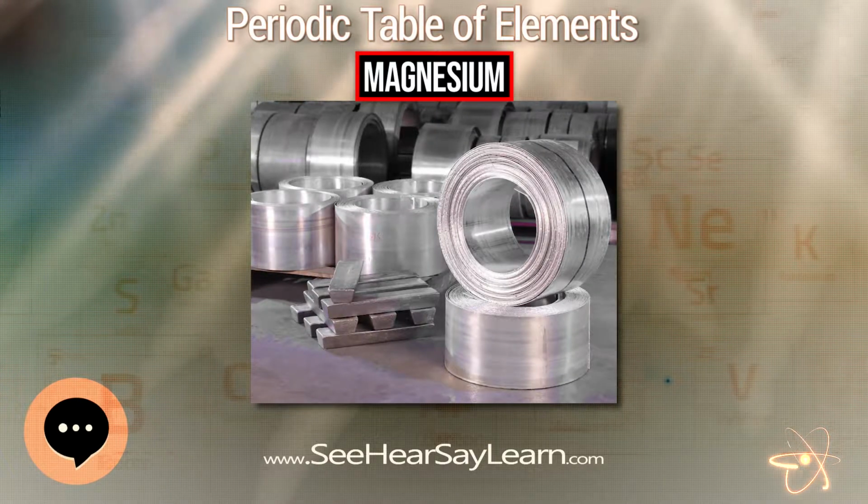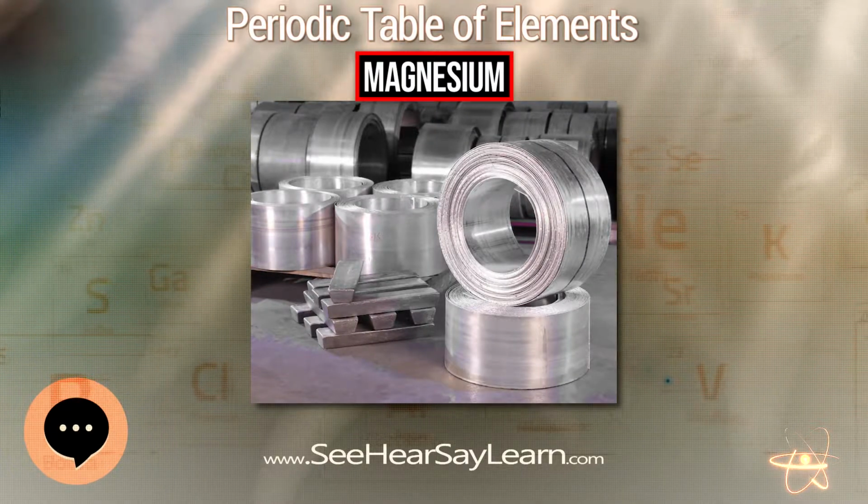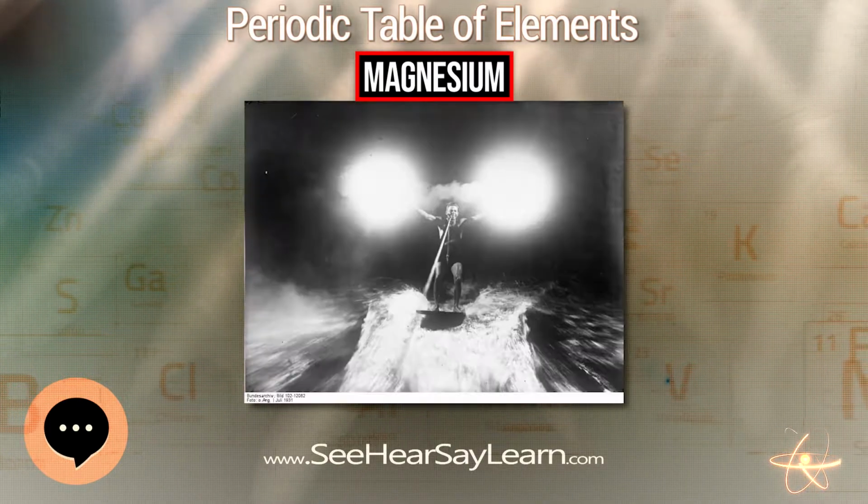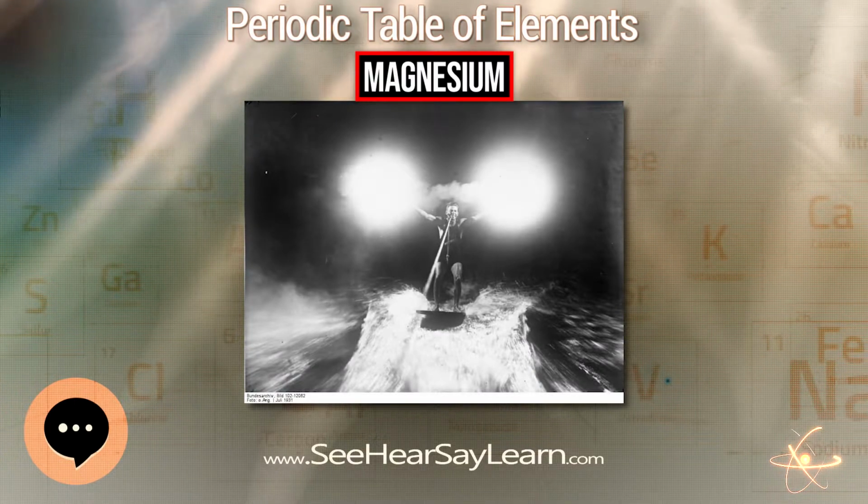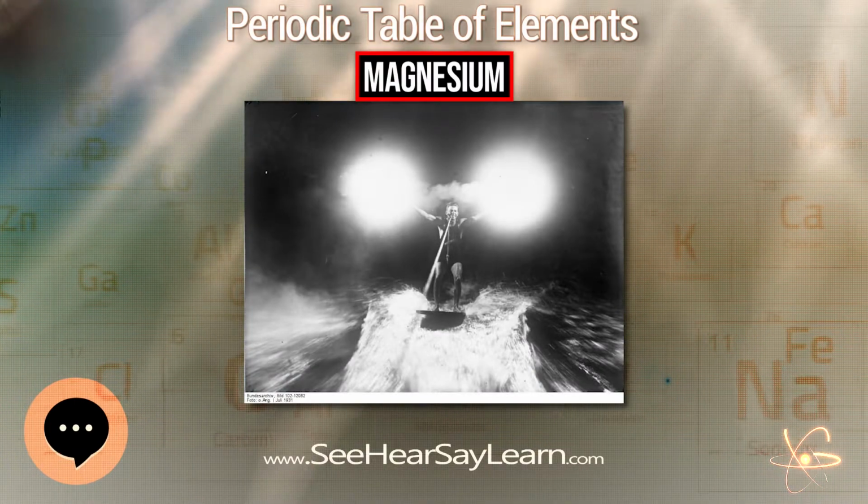Burning magnesium can be quenched by using a Class D dry chemical fire extinguisher, or by covering the fire with sand or magnesium foundry flux to remove its air source.